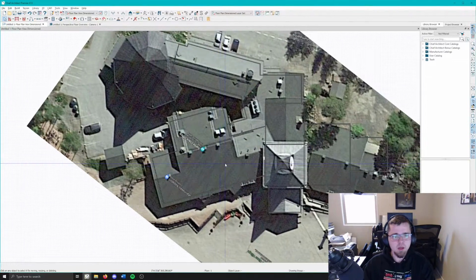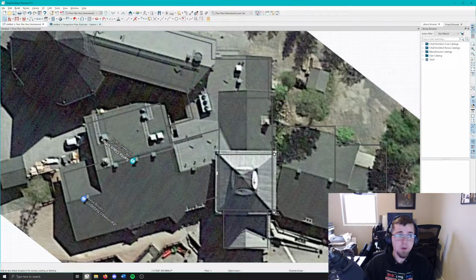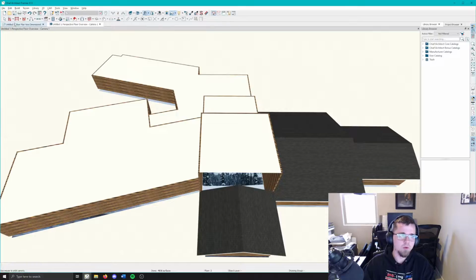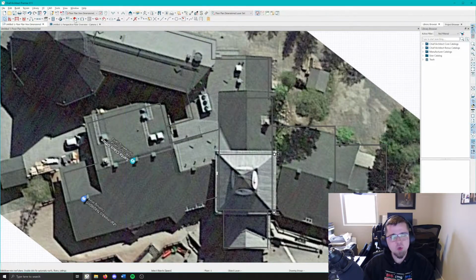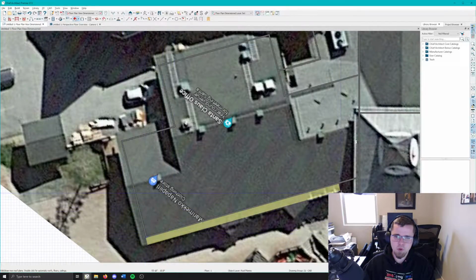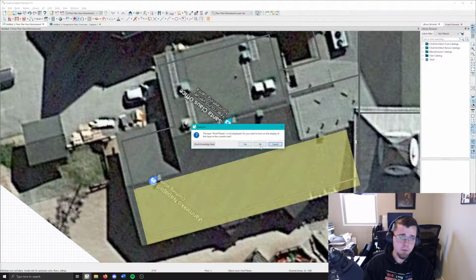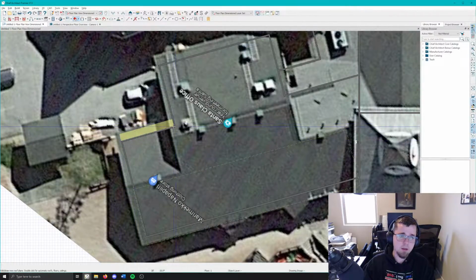Once we have it fully sketched in, at least the footprint of the home and the roof line, we'll add in all the windows and the doors at the foundation. Generally, I don't add the roof until we have the floor plan completely worked out, because it becomes a lot of work to adjust all the roof lines if the roof was tricky. And usually the roofs are pretty tricky. This one is obviously very simple, just all gabled. You don't get much simpler than this, but most of the time there's some complexity to it. And with that complexity comes even more complexity trying to fix or adjust things after we've already drawn them.